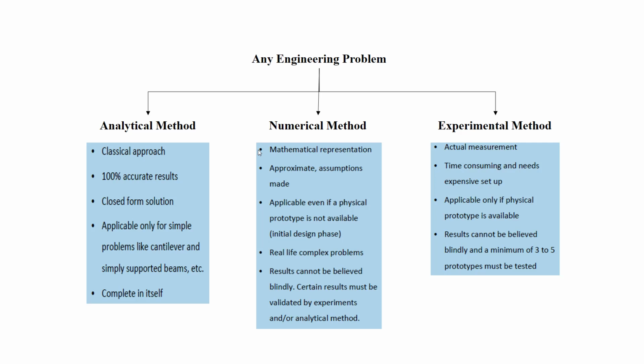In order to perform experiments, you may need to destroy the product. So it is a very expensive process, and likewise a time consuming process. And it is only applicable for physical prototypes. Results cannot be believed blindly, and a minimum of say 3 to 5 prototypes must be tested in order to find the accurate behavior of the particular product through the experimental method.